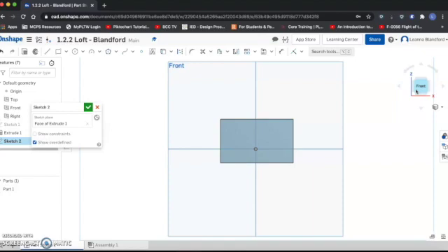Now the trick is, if you look at the drawing on slide 52, we have 2 vertical lines that we have to create, and they have to be equal in terms of the angle from each other. And they have to be a certain distance from the left, right, and bottom edges. So in order to find that distance and get those lines to be constrained properly, we need to start by creating some construction lines to guide our drawing.